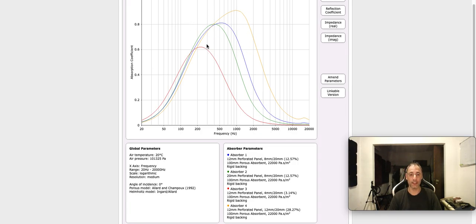Of course, just to say that all these four configurations, they roll off in terms of the high frequencies, and they all roll off in terms of the low frequencies. But the low frequencies are controlled mostly with the absorption and with the air cavity that you place behind the panel. So what we see here is that in these four configurations, this area over here is drastically different for each panel, but this area over here is almost identical because the materials behind the panel are the same.